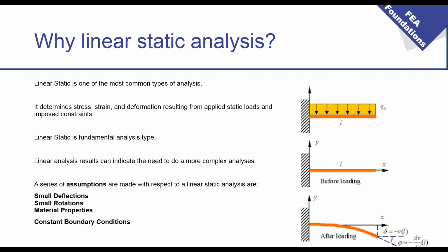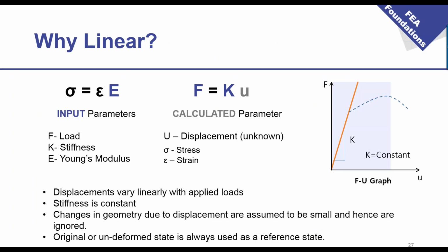If you take a look at this picture, the rotations should also be a very small percentage of your model. Usually we measure this angle using a trigonometric function, so the tangent should be almost equal to the angle, which means the angle should be very, very small. We also have to take into account the material properties and constant boundary conditions.